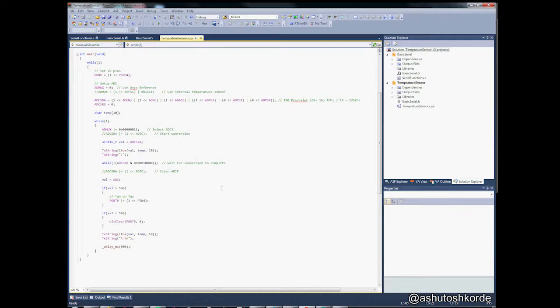And that's about it. This program is tailored to the circuit that I have developed on the breadboard, which only has one thermistor and one fan. I'll go ahead and change this program so that it can support up to 3 thermistors and control up to 2 fans. The circuit would be exactly similar to what we have in there, except that we'll have two transistors that will control 2 separate fans and 3 thermistors connected to 3 different ADCs on the microcontroller.